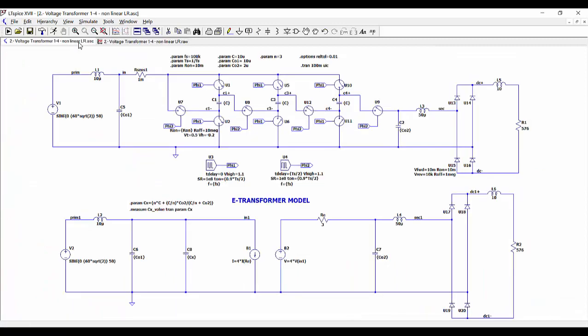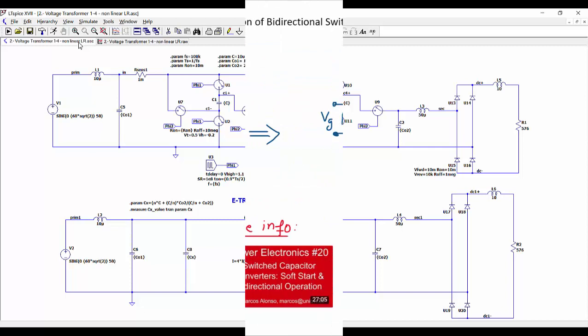So we can see that our circuit, our transformer, can be applied in many different situations because the dynamics of the transformers is very good. It's in the range of a few microseconds. So as long as we use at the ports of the transformer loads with a dynamic much slower than our transformer, in principle the circuit is going to behave well.